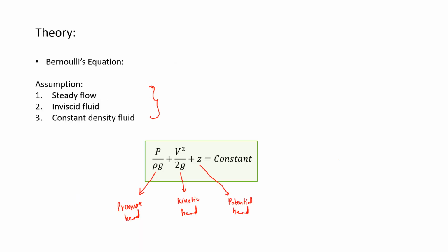So you need to apply the Bernoulli's equation here, and we had seen the Bernoulli's equation. One good hint is always keep in mind these three assumptions, and wherever you see in the question that these three assumptions are being mentioned, then you should already get a hint that this might be a question where Bernoulli's equation can be applied to solve for the answer. So assumptions are steady flow, inviscid flow, and constant density flow.